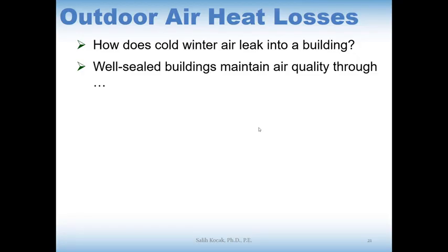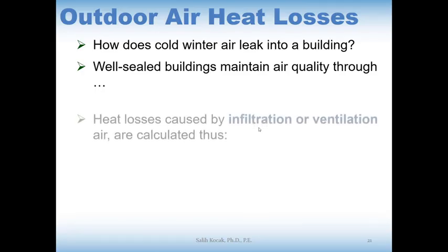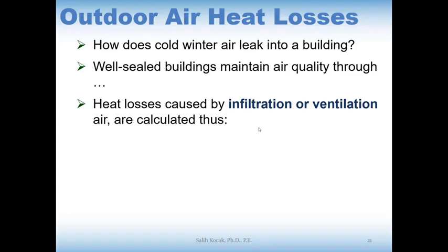And heating equipment must be sized to heat this admitted outdoor air. Heat losses caused by infiltration and ventilation air are calculated. How? By using this. CFMs are calculated through the infiltration or ventilation.